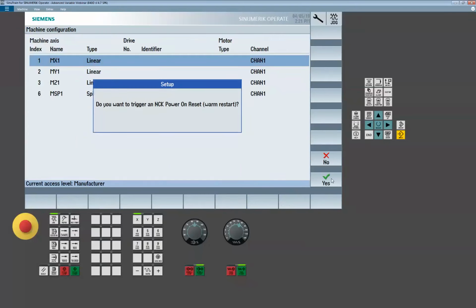So if you're chasing a problem, step one is you have to figure out where the alarm or the problem is coming from. So hit program levels. Right now I see my safe position 2 is the program that I'm actively running. Once I come out of that one, see how it jumps back to the main program? I'm back in my main program.